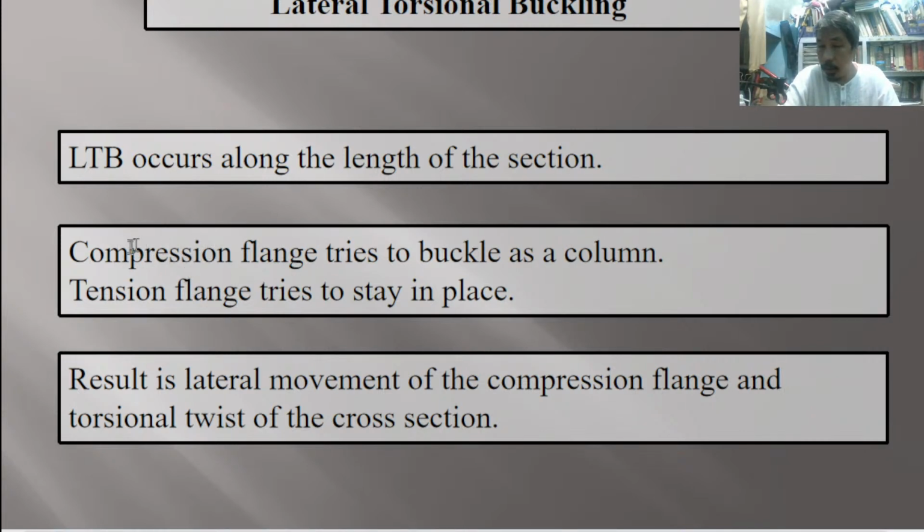That's why we tackle compression, we'll tackle buckling, global buckling, local buckling when we are under the compression members, but not when we are discussing tension members. So these are the flange reactions. So compression flange, usually this is on the upper flange, the top flange, and then lower flange tension.